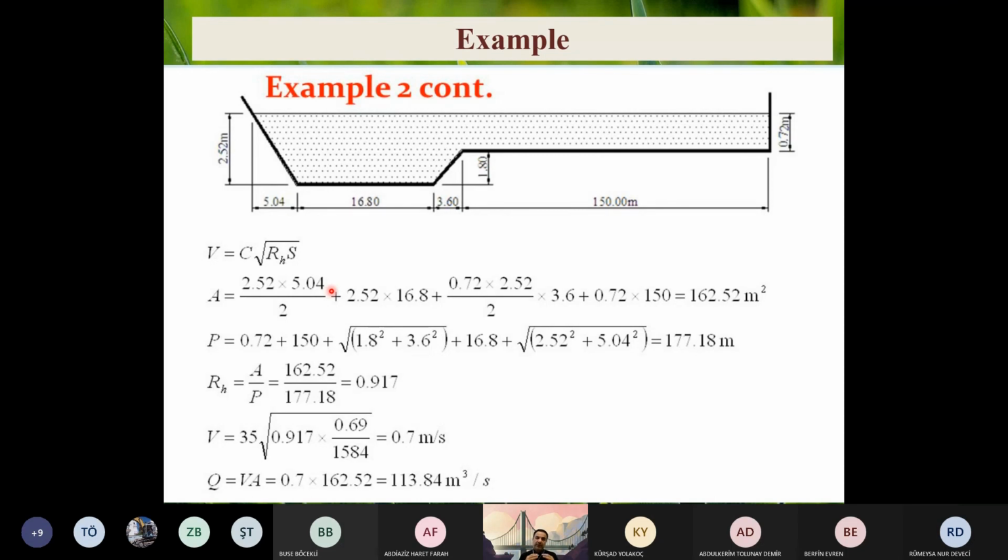But when this separation does not provide higher accuracy, and we simply calculate one hydraulic radius, as you saw here, maybe it gives us an answer close to the real value, close to the correct one. It is also acceptable. But this solution, as you see here in this example, is an approximation. Definitely the real discharge is not this one, because we approximated one hydraulic radius for this cross section.